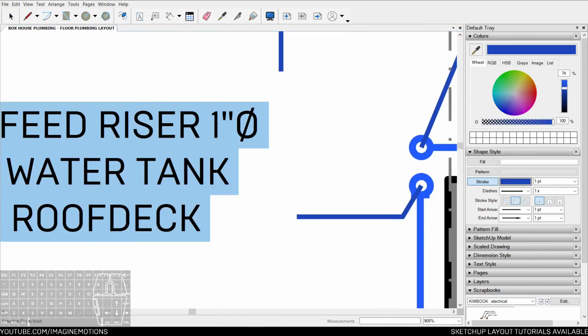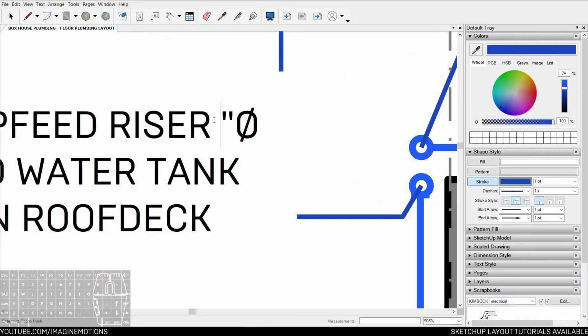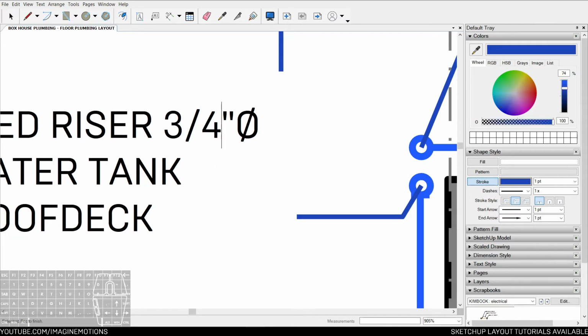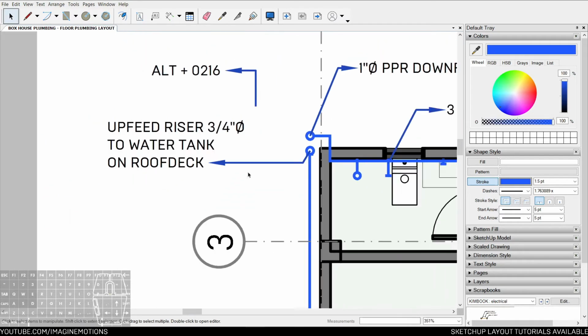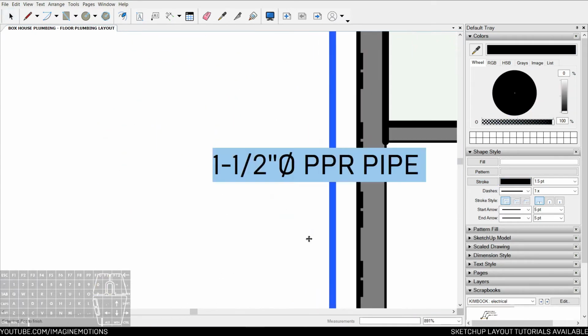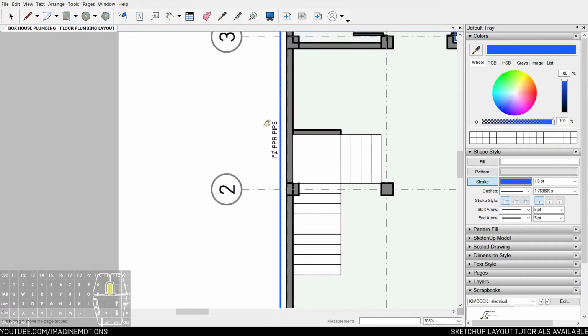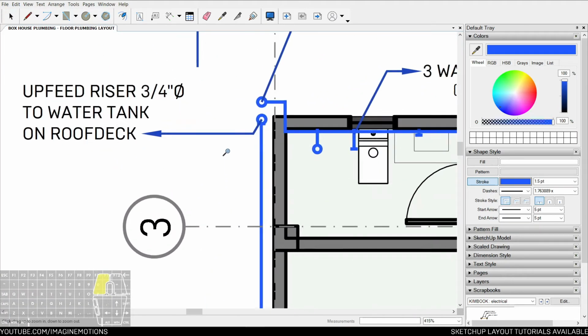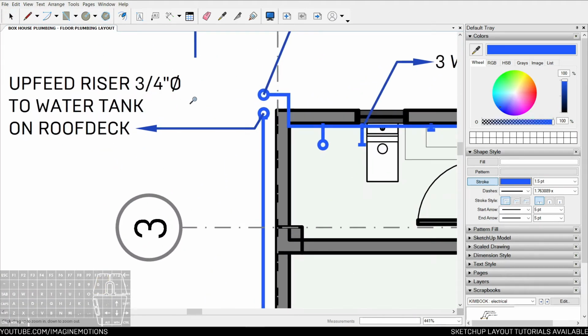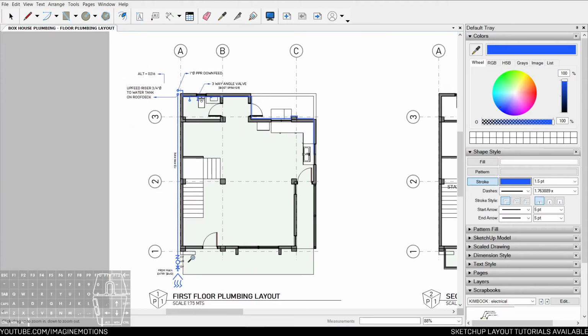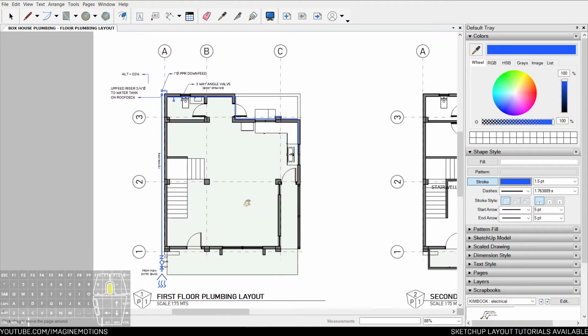So I can make it smaller by making it 3/4, depending on also the design. So let's say I have this as 1 inch, so water flows smoothly. And when it goes towards the riser, I need the pressure to build up to go to the 3rd floor without having a pressure tank.